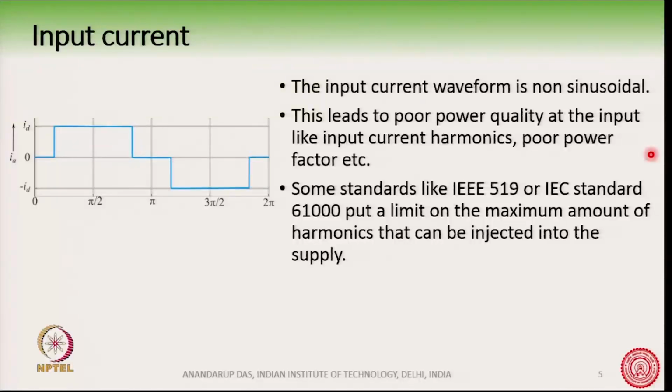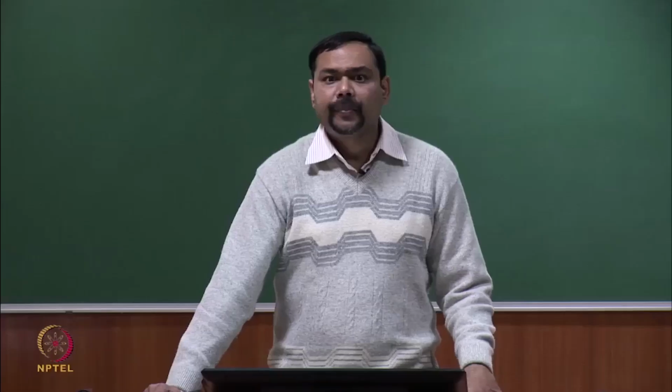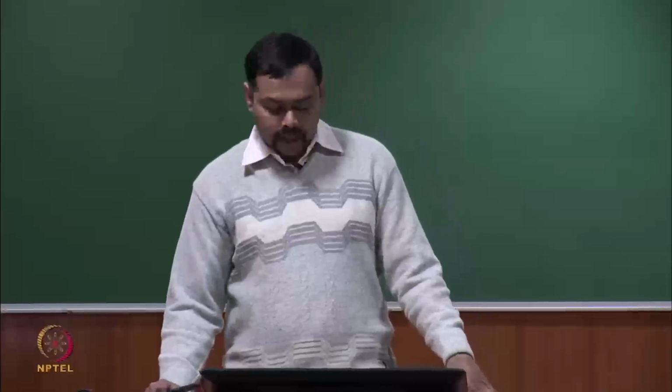Typically, IEEE 519 says that something called THD, we will explain that THD, should be less than 5% of the input current.